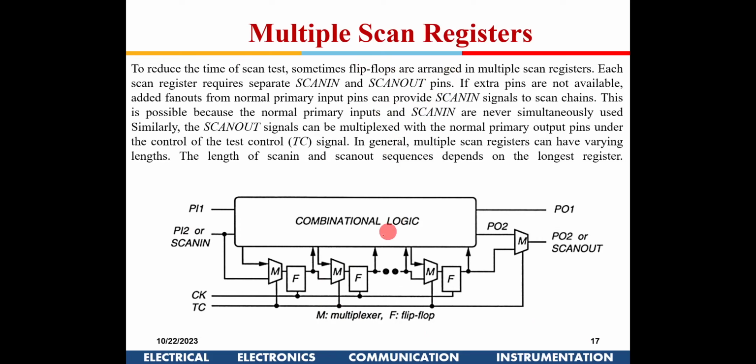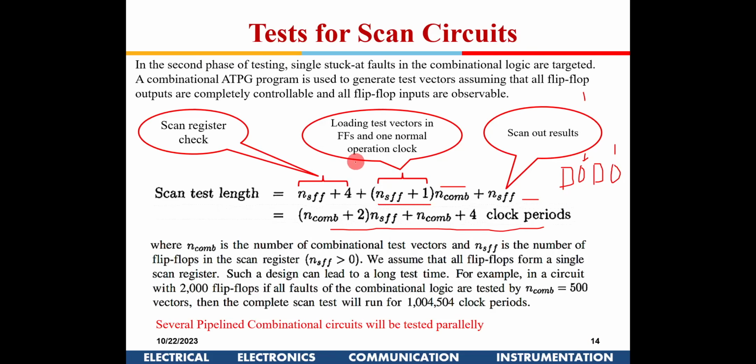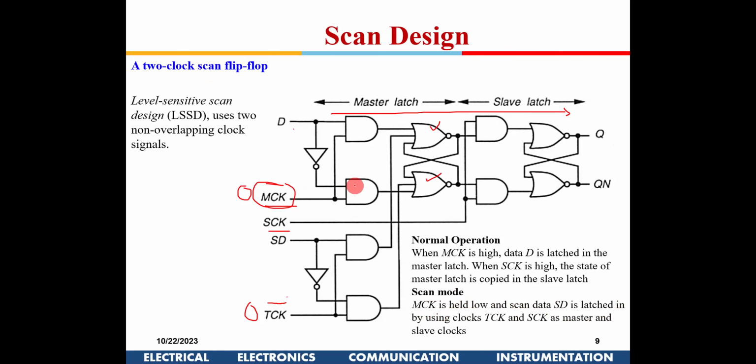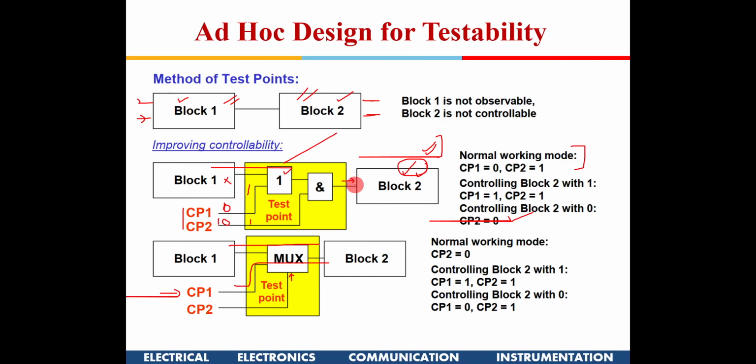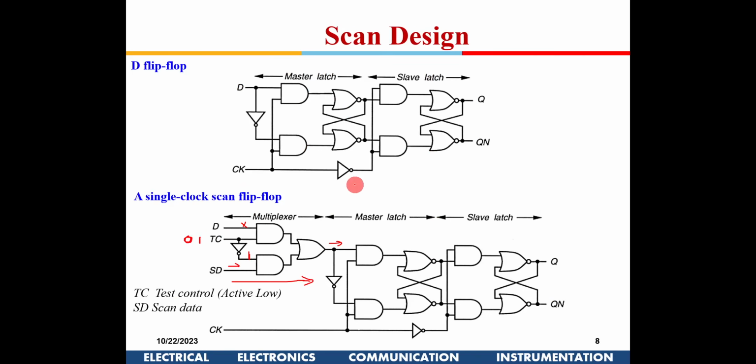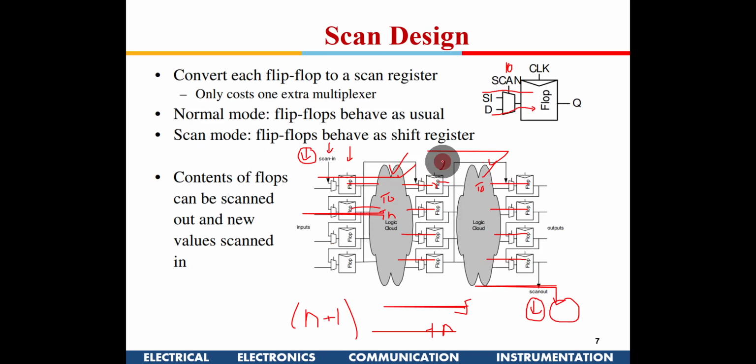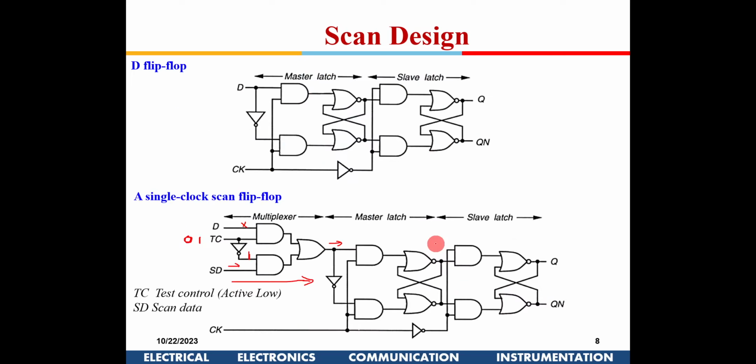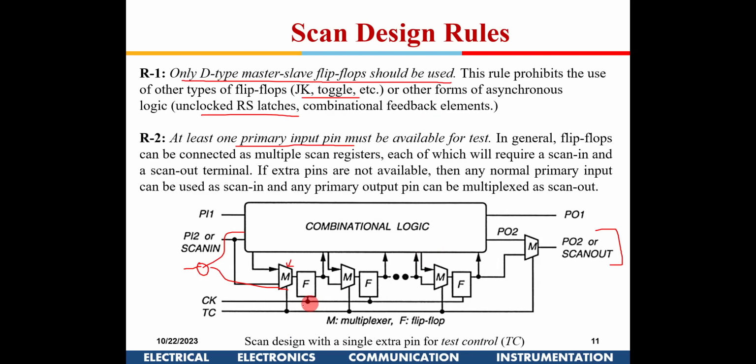And this is just telling that instead of having individual flip-flops here like this, you could have a single big register, so that this routing problem is a little bit avoided. Obviously, registers will have multiplexers incorporated.